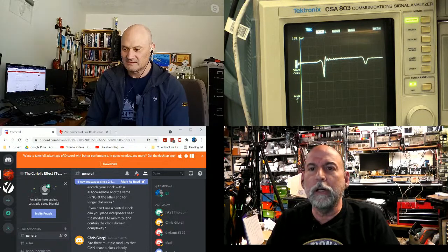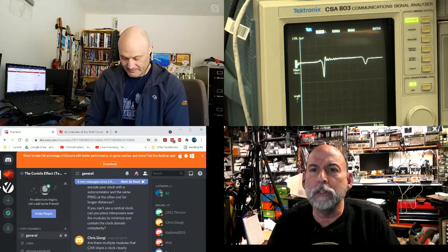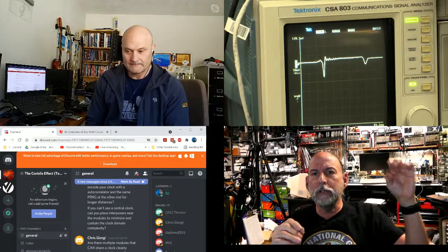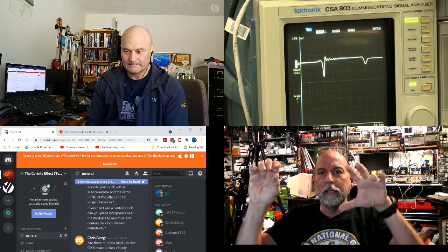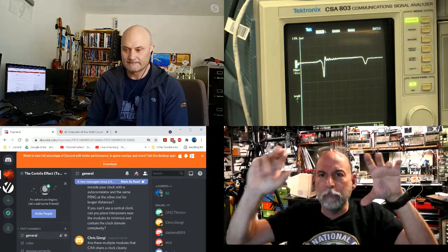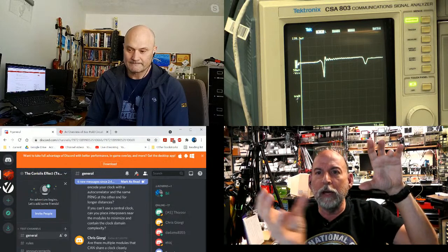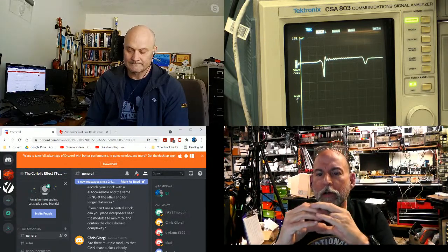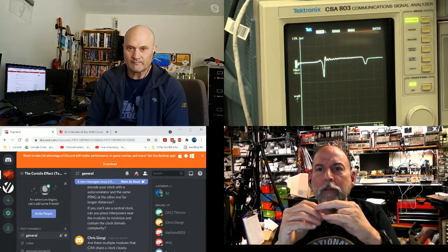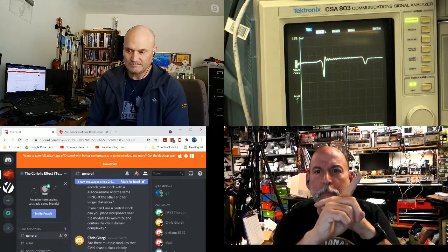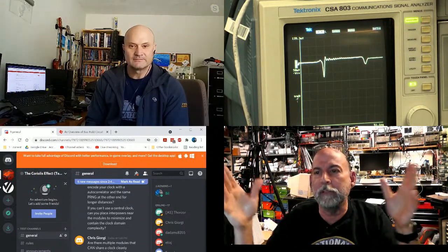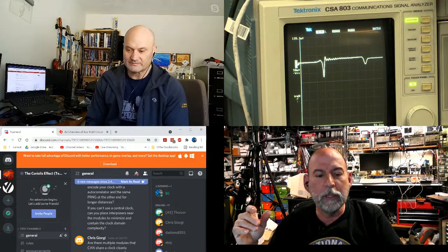So you mentioned FPGAs used as DSPs. What you can get a lot is, here's a process flow, and here I need some memory, and here I need some memory, and here I need some memory. And generally you won't have a DDR interface for each step along the way. You have to share a common pool of DDR memory. So how do you make it look like its own dedicated memory to all 3 sources, up to 7 typically on the IPs I've seen?